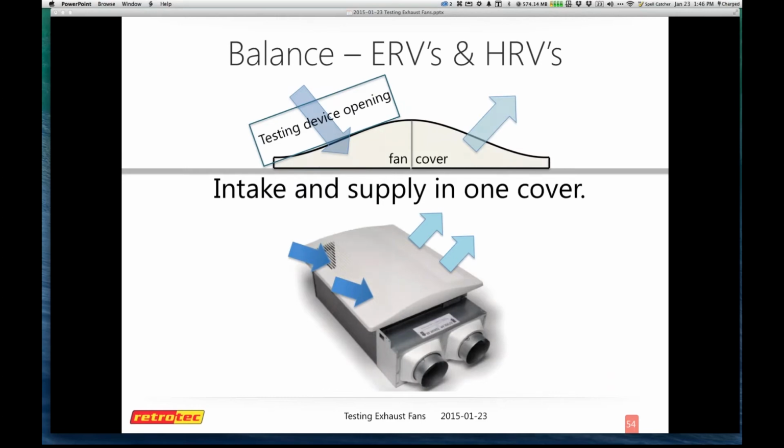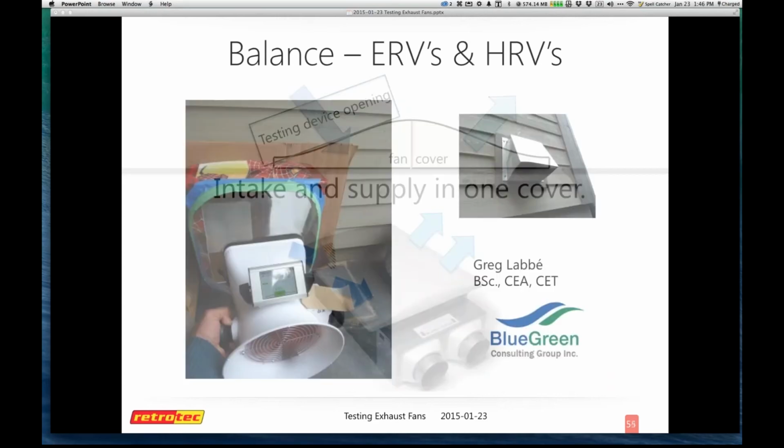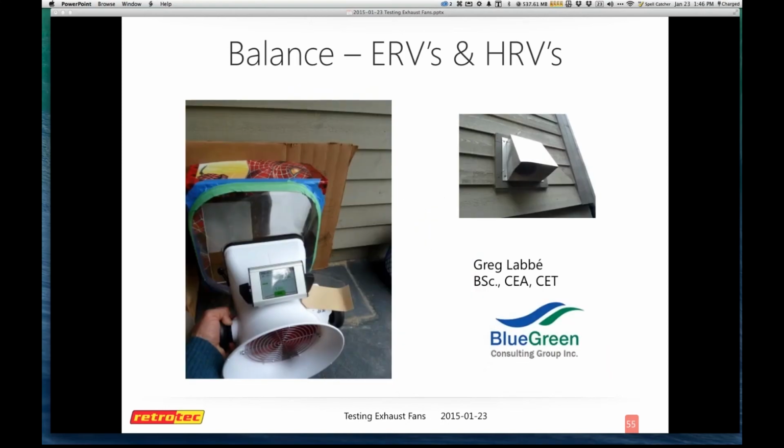So depending on what your device is, some people are going outside trying to do that. This came from Greg, I believe he's up in Canada. Greg maybe was today. So he has the ability to try to use the exhaust fan flow meter, the FlowFinder, because it does a great job of receiving air directly.